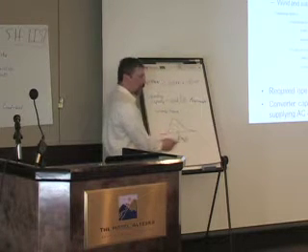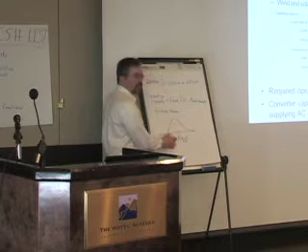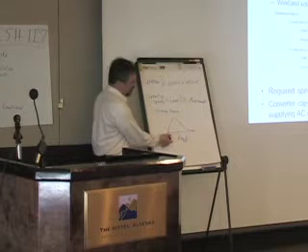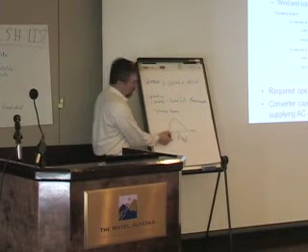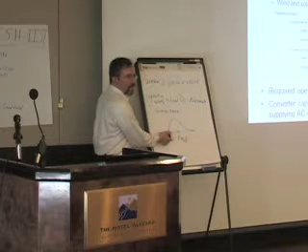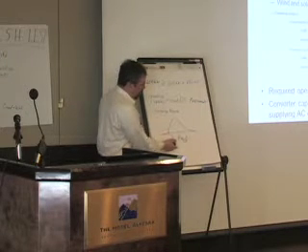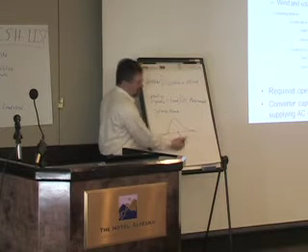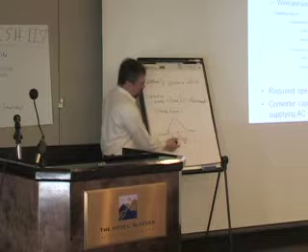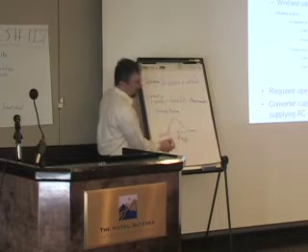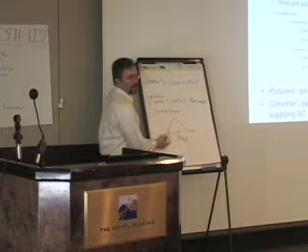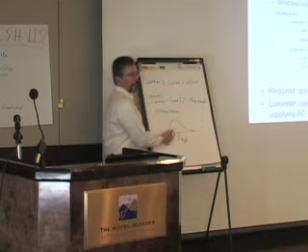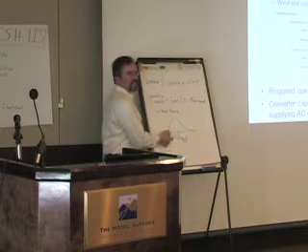But then we have to say, okay, where are we cutting it off? There's some probability that the wind's going to drop below some number here, and we define the operating reserve that's required by how much the power output drops between here. But we also have to define the constraint somewhere. So it does that by asking the user for a loss of load probability. How far out on the tail do you want to protect yourself?